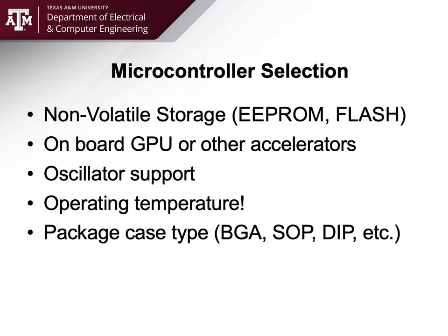It is literally a ball grid array: little tiny solder balls on the bottom of a chip array, on a small circuit board where the actual chip die is soldered and hardwired with gold wires to the die, and these little solder pads. Typically on an array of 0.8 millimeters by 0.8 millimeters, and typically somewhere in the neighborhood of 1,000 pads. If you're planning to solder that by hand, good luck.